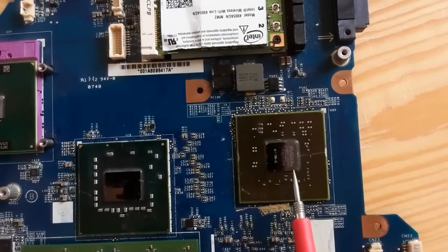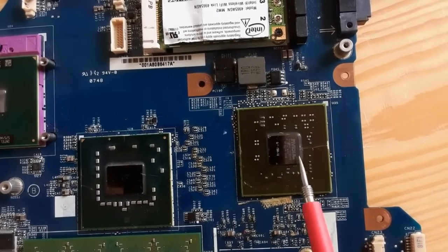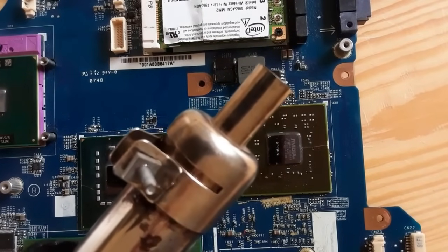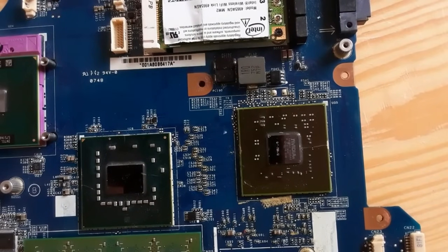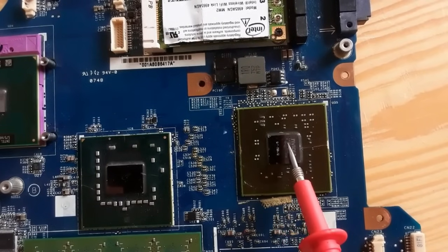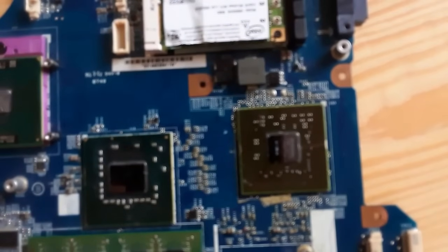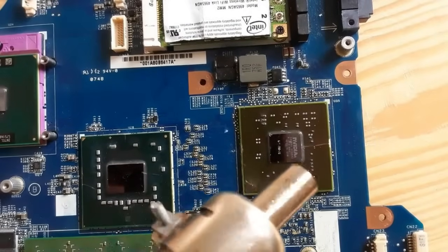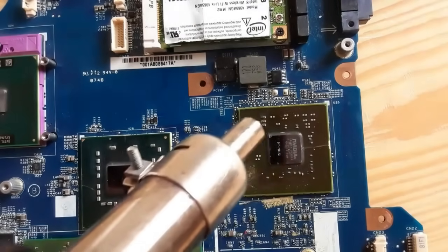Now I'm going to show you how to repair the graphic card problem. Sometimes you can get a laptop with no data or nothing on the screen. The graphic card is one of the common faults that can cause this problem, along with the RAM, the random access memory. If you have no data, you check the random access memory and the problem still persists, you should apply hot air or heat to the graphic card, as you can see.